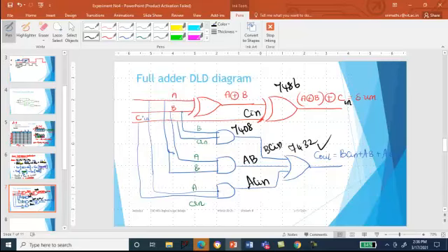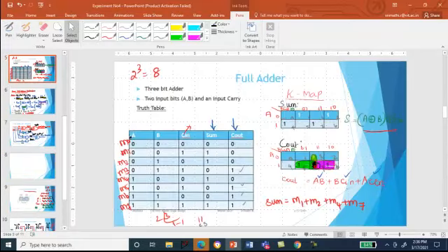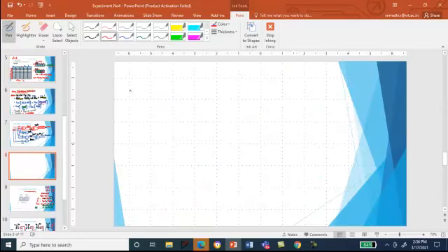Now let me come ahead with the signal description that we need to use in LTSpice. Look at the inputs. You have 40 and 41 for A, 20 and 21 for B, and 10 and 11 for C. For each transition, we take 1 millisecond.